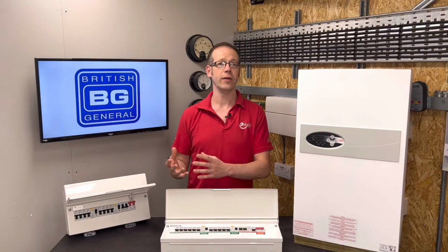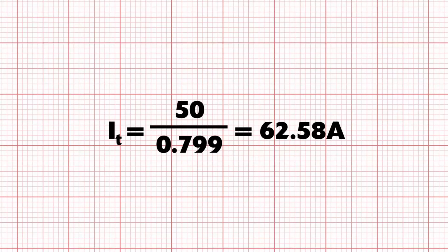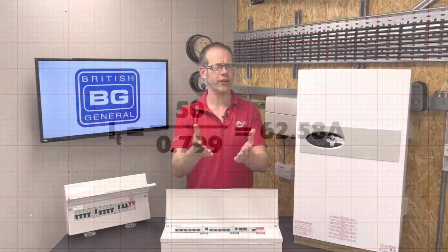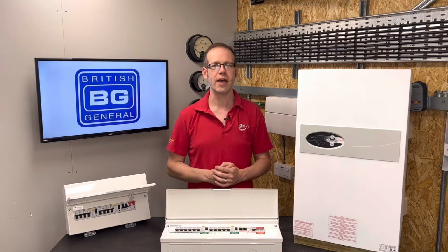Well, in the last video, the previous step was to calculate what the tabulated current carrying capacity of the cable would need to be. Remember, tabulated just means recorded in a table. So let's find those tables. We'll stick with Appendix F in the on-site guide.